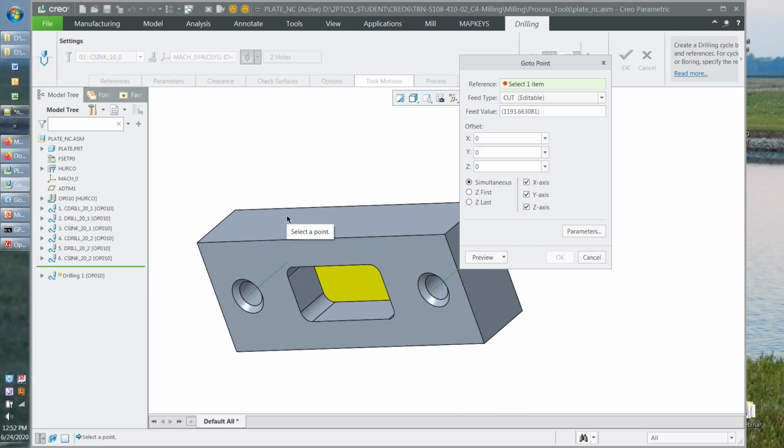And it assures it consistently because the post is always going to solve for shortest rotation by default. The problems come up when the rotations across A and B are the same 180 degrees. So that's where you need to start thinking about how you're handling it on the Creo side, not necessarily fighting it with GPost.